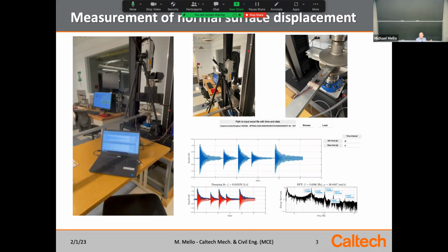And then the magic is really in the FFT, which I'll talk about more in depth later on. In the lower right, you can do an FFT analysis of the very signal you've just collected, and out will come these peaks, which seem to emerge from all of this heavy muck. All of a sudden, boom, out comes this spike, and then more of this stuff, and then boom, out comes another spike. These are the dominant frequencies present in that vibrating structure.